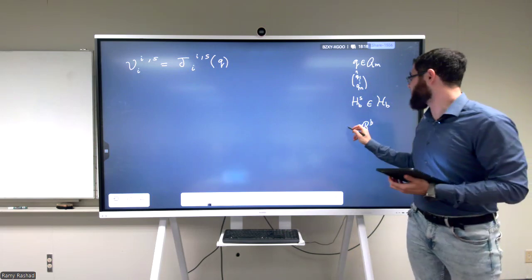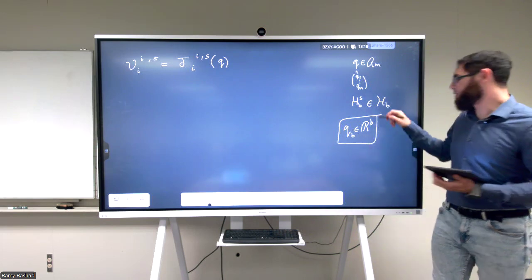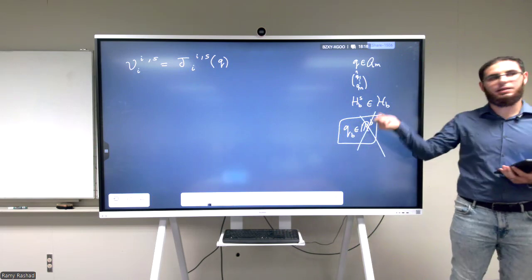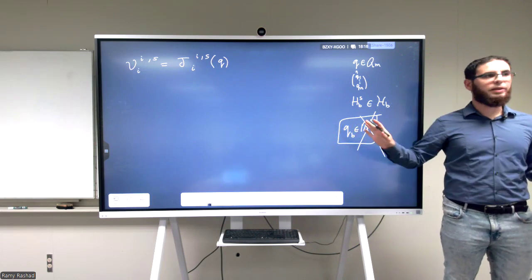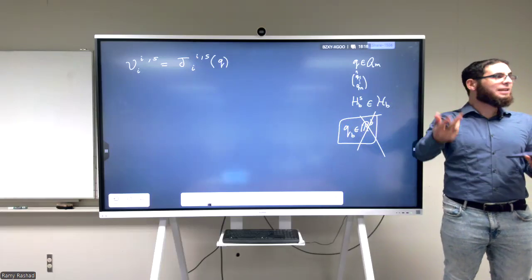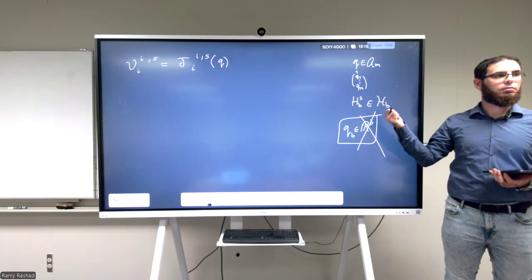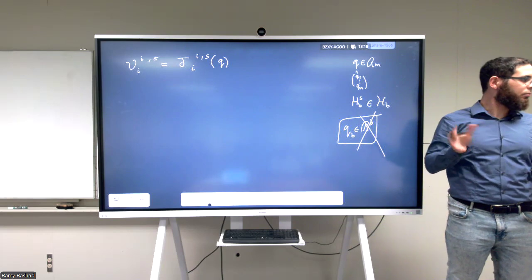So let's introduce something maybe like the Q of the base in RB. And this is completely not geometric. So whenever you find something like this as a starting point that says I have QB, completely not geometric. Because they're assuming here that I can represent the base movement by 6 numbers. And you know that's not possible. It's definitely not possible. For a planar joint, for a floating joint, we cannot do that.